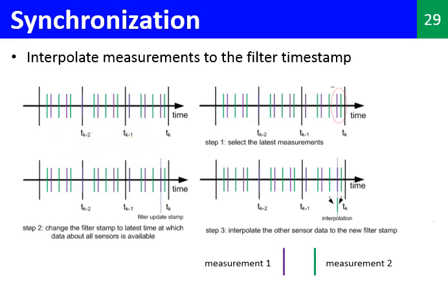Now there will be separate threads running for sensor measurement callbacks. For example, say we have a camera sensor that gives measurements at 30 Hz. Furthermore, we might also have an IMU sensor that gives measurements at 50 Hz. So they will have parallel threads to update the incoming measurements.